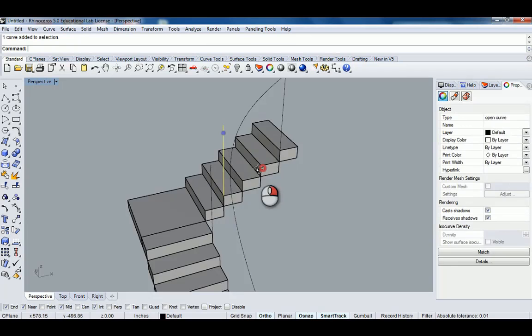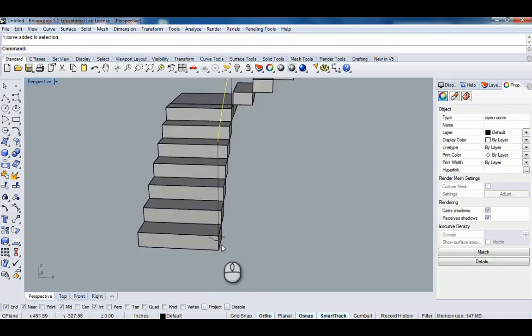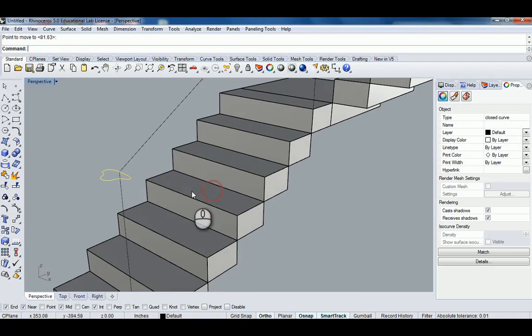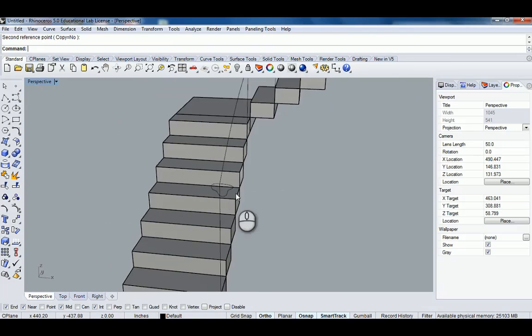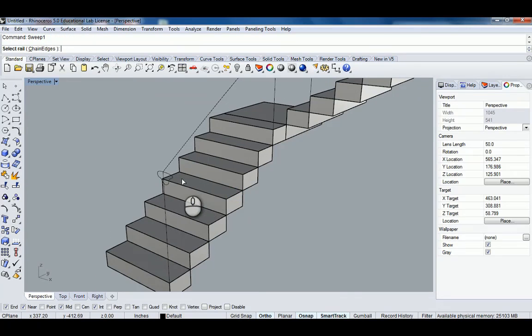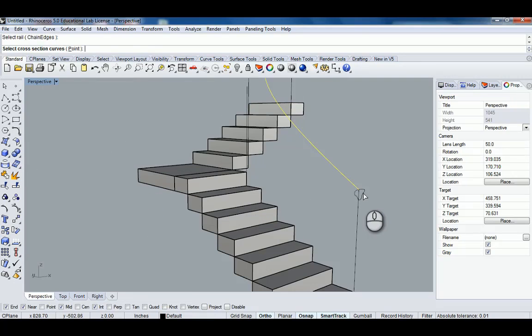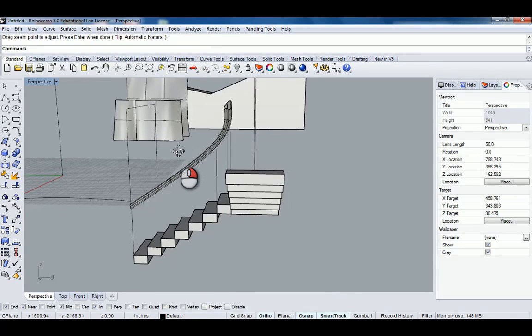So let's say we want to get this to extrude the way that you were describing. Because we've started to twist those points, I think what's going to happen is what you were encountering, where it twists on itself. So let's try to troubleshoot that. All right, so I'm going to say sweep 1. I'm going to say select rail. I'm selecting this curve. Now I'm going to select this cross section. And you're right, it angled it, right? Which is not what you wanted.